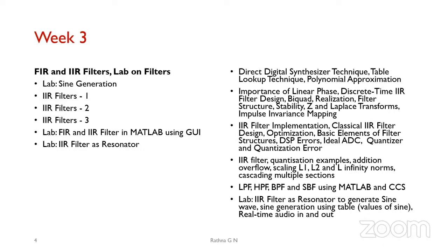We can allow a little leeway in the pass band, but the stop band cutoff should be exact, because if we deviate a little, higher frequencies may creep into the pass band region. It may cause instability to the system, or an aliasing effect in the frequencies. So this has to be taken care of. Whereas we can go for the bilinear mapping, only we have to do the compensation for whatever we have taken care of in designing it.